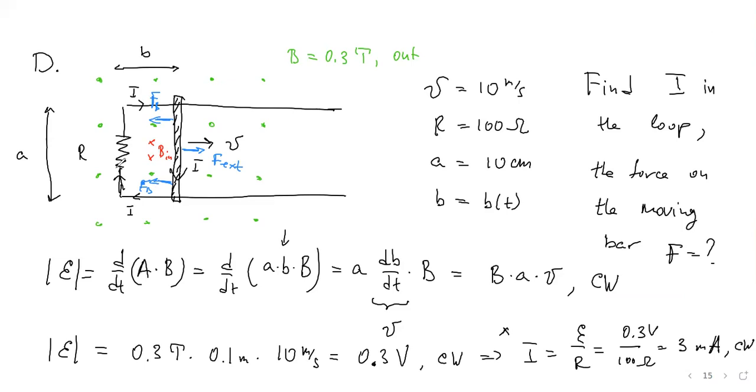So when you move this, it will be hard for you because you actually produce the current and you produce the heat in the resistance. This is already like a generator. Maybe it's not a very effective construction of a generator, but this is a generator. You convert mechanical work to electricity.